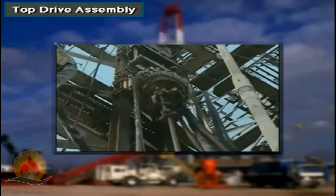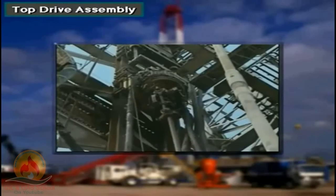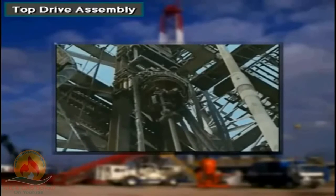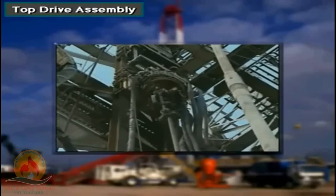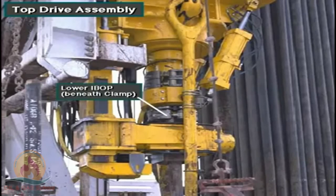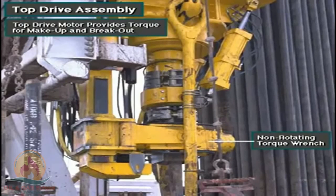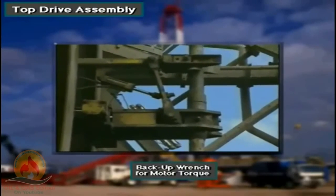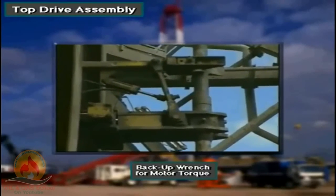Service loops, which are bundled cables and hoses, transfer the required electric, pneumatic, and hydraulic power between the mast standpipes and the junction boxes located on the top drive. The top drive unit also includes a pipe handler assembly that has an upper inside blowout preventer, IBOP, a lower IBOP, and a torque wrench. The torque wrench makes up or connects and breaks out or disconnects joints of drill pipe.